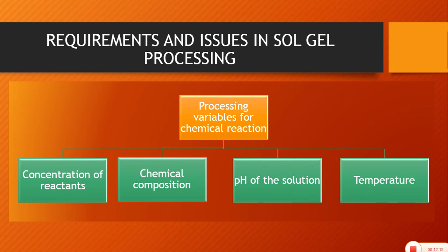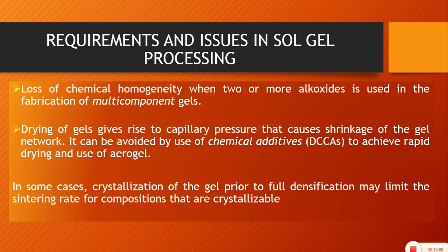Here, another problem is the drying. During the drying or evaporation of the gel to form the xerogel, under certain normal conditions, it gives rise to capillary pressure that causes shrinkage of the gel network. In the resulting dried gel, that is the xerogel, the capillary pressure is quite large, and it is larger in a polymeric gel because the pores are normally much finer than those in a colloidal or particulate gel. Consequently, severe problems can be encountered with the warping and the cracking of the gel. So there are two general approaches.